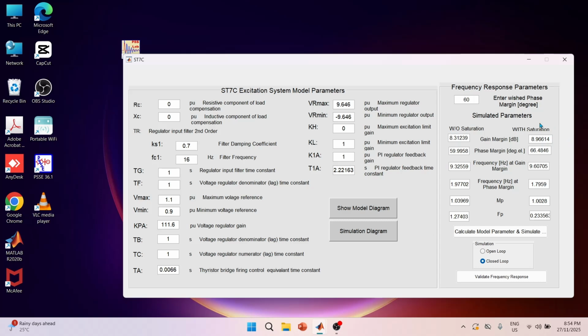These control parameters such as gain margin, phase margin, maximum amplitude in the closed loop are important to ascertain the quality of the frequency response and compare with those given in IEEE standards for excitation systems. We can notice the control parameters with saturated reactance provide slightly more gain and phase margin. For example, the difference in the phase margin is around 6 degrees more with saturated reactance.